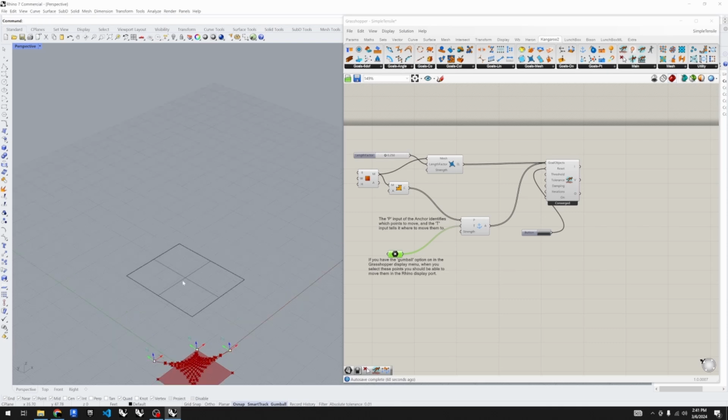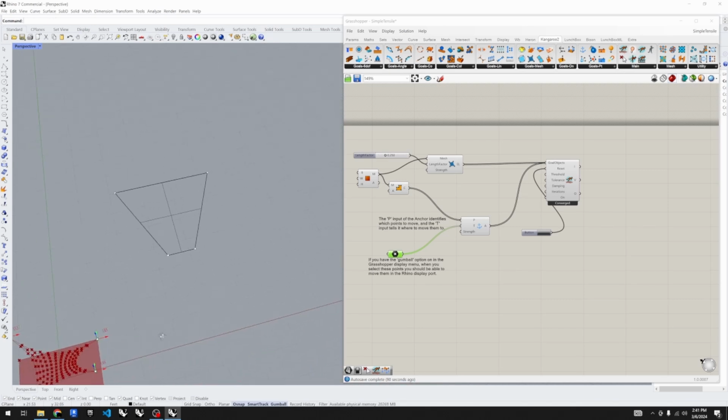I'm going to do something maybe like that. I'll click on this surface and hit F10 to show my control points. I'll select both of those control points by holding down Shift while I select them. I'm just going to scale this in to make one of my petals. Then I think I'm going to shorten this up a little bit, maybe something like that. Great. I'm going to hit F11 to hide my control points.